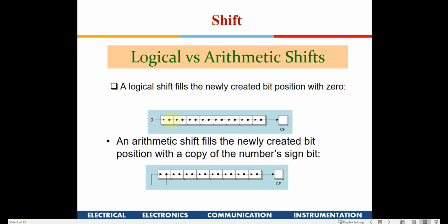That is known as a logical shift. Whereas an arithmetic shift means whenever we are shifting to the right, whatever was the previous MSB, the same thing will be held there. If it were a 0, it would be 0 again, and if it is a 1, it will be a 1 there. Essentially the sign of the bit will be preserved.